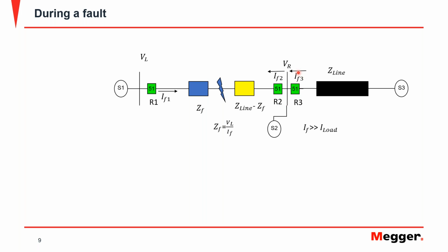But in this particular condition, we are also taking out of service this source, which may mean that the system that's left may not have enough power to serve the customers connected to this line, and this could create a cascade of issues in the system.